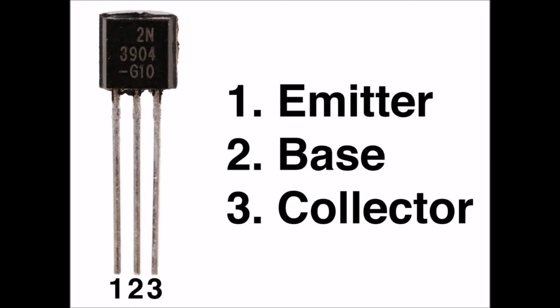Top of page 378. Amplification. Because a small change in IB causes a large variation in IC, when we set the DC bias voltage properly, a transistor can operate as a current amplifier. Engineers use several expressions to describe the current amplification characteristics of a bipolar transistor.